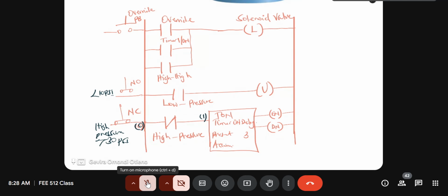So, like in this case, somebody might decide that they're not going to, you see, typically we would latch the circuit, but now you can see the conditions that we have here and how many they are. So it's very difficult, and we don't have a normally closed contact or a stop push button. So we can't latch it the normal way. It's difficult for us to latch it in the conventional way. Remember, we talked about the 2 different types of latches.